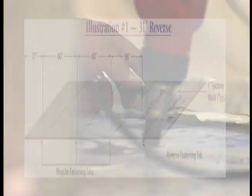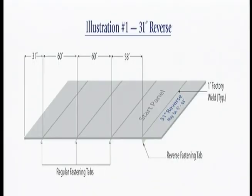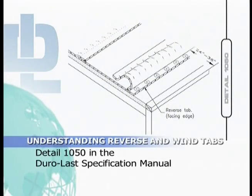a snapped chalk line. This illustration shows a Duro-Last deck sheet with a 31-inch reverse tab. A reverse tab will be located from 6 to 63 inches from the beginning of the deck sheet. The measurement is taken from the beginning of the deck sheet to the factory weld. Therefore, this illustration shows a 31-inch reverse tab with a 3-inch fastening tab on the underside of the deck sheet. Detail 1050 in the Duro-Last specification manual shows a deck sheet with a 31-inch reverse tab, placing the fastening tab 24 to 36 inches from a roof edge. This is helpful in satisfying Duro-Last wind specifications.